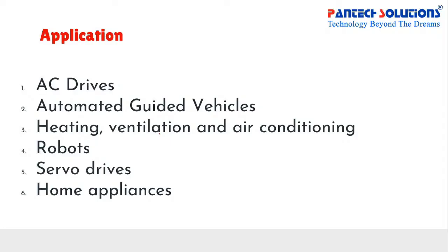If you take robotic applications, to handle a huge amount of load, the PMSM gives the perfect solution. And servo drives for industrial applications, like the food processing industry or textile industry, wherever DC servo drives were used earlier, we can replace them with PMSM machines. And again, home applications, AC, washing machine, and fridge, we can replace smoothly with the PMSM.